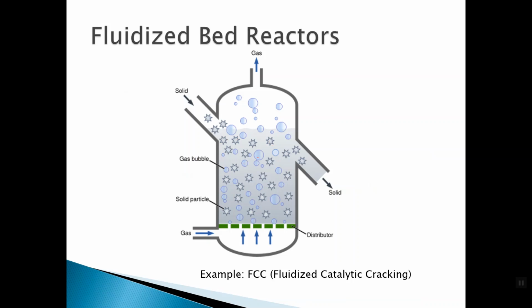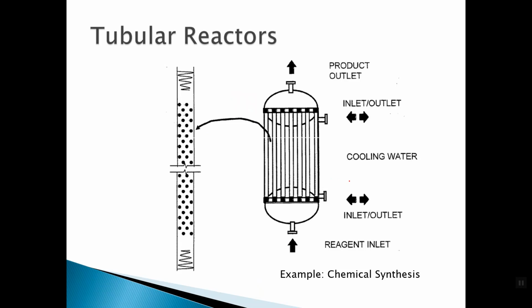Fluidized bed means we have this solid, our catalyst, and instead of having it fixed into one place like we do here, this is constantly moving around. It's in a fluidized bed, so we have solids all moving around here. And notice there's no agitator in here, because as those solids are moving around, they're agitating the material. And so they're coming into contact with our gases, with the material that we're trying to react. So the raw materials come in and then go out as a final product.